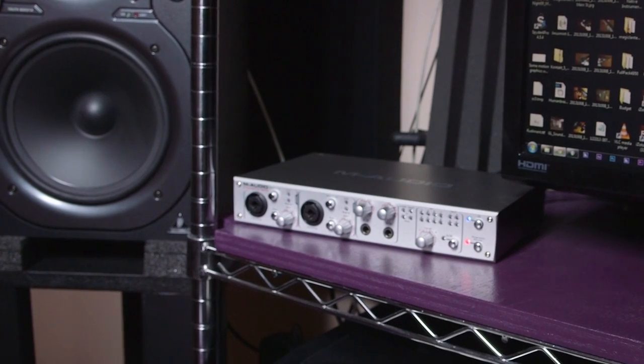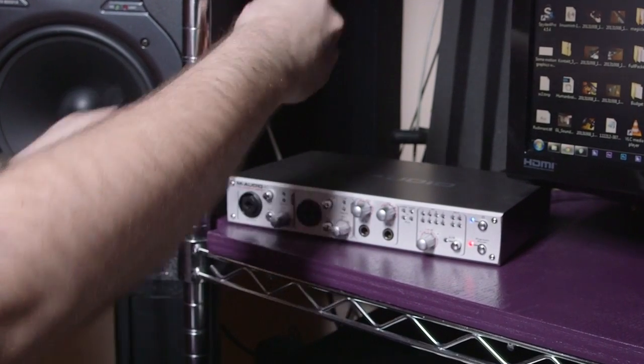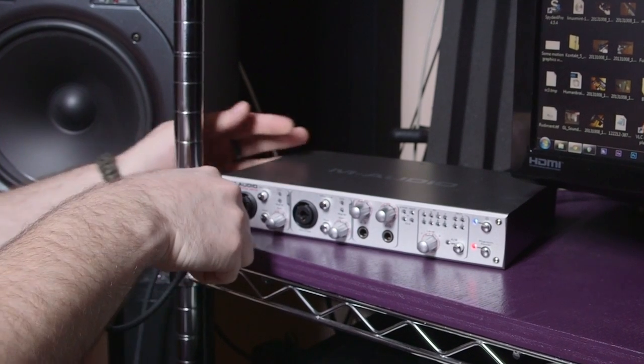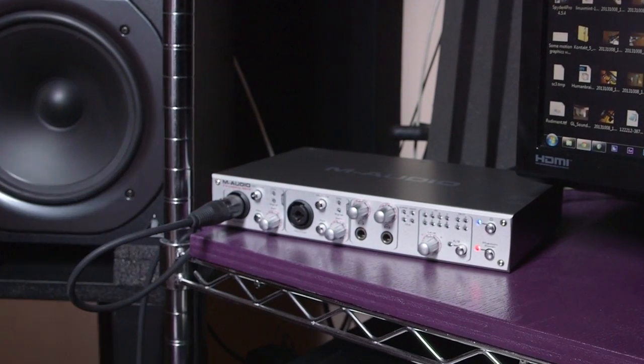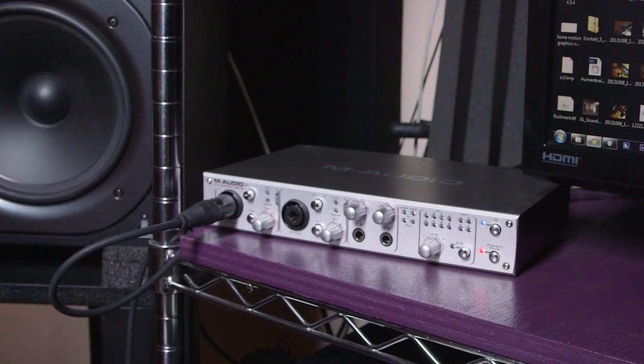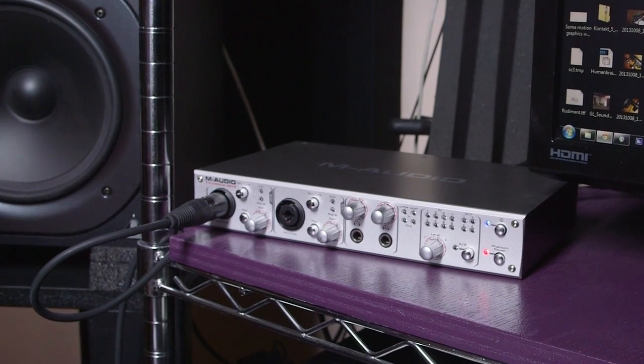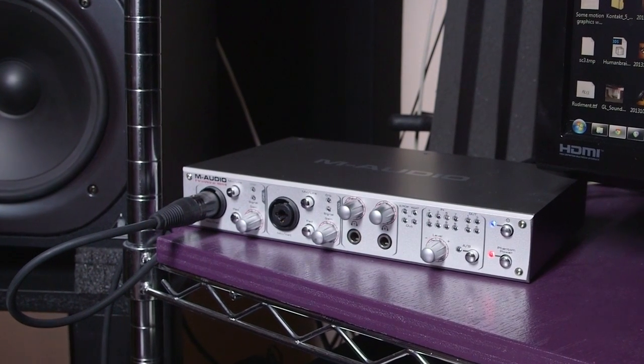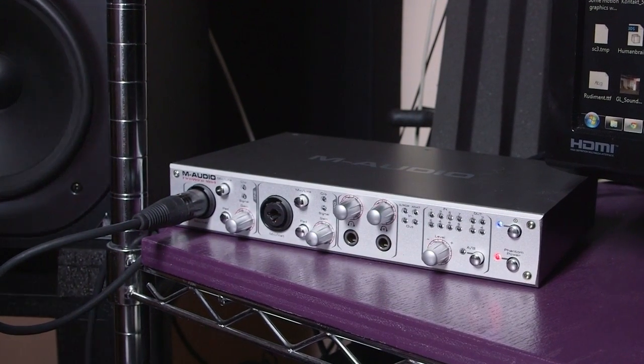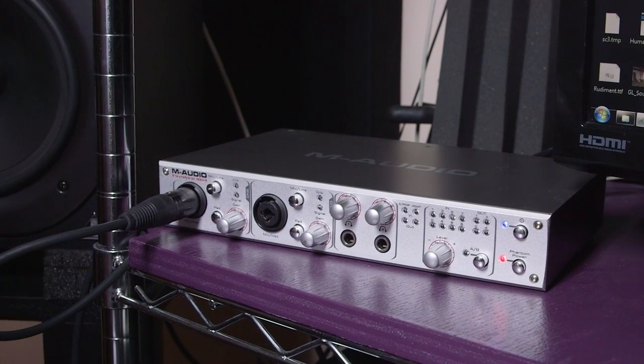I also like to put a little strain relief when I plug the cable into my interface. I do this by creating a little slack and then have the cable come into the interface from a nice, gentle arc. Cables can be damaged if you bend the cable very severely. XLR cables are quite flexible, but I like to be extra safe. This also protects the input of the interface from being damaged if the cable gets snagged or pulled. This kind of force can damage the solder joints on the XLR connector, which will need to be repaired.